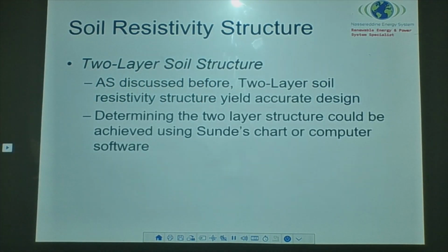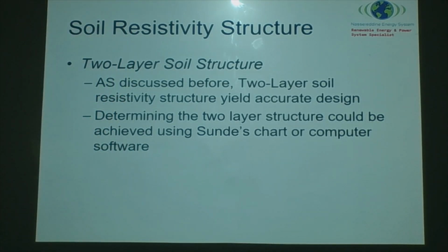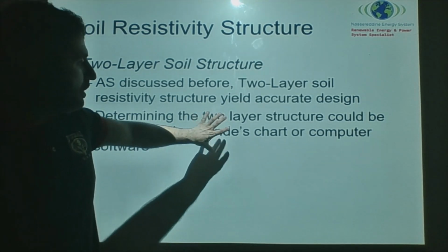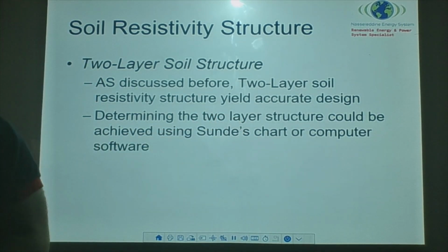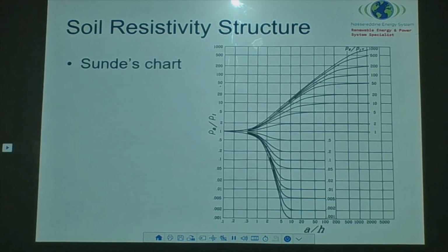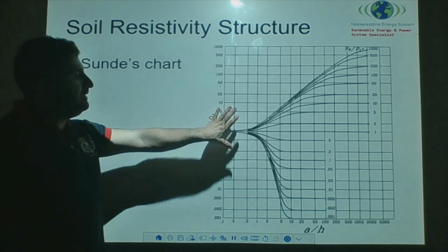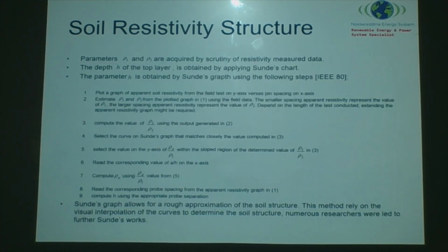Determine the two-layer soil structure using hand calculation. You want to use Sunde's chart or computer software. Like we spoke today, we are going to rely on hand calculations, Sunde's chart. This is based on IEEE 80. What do I need to do? All these steps.